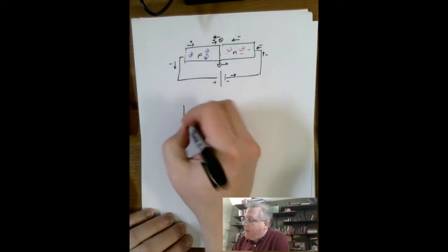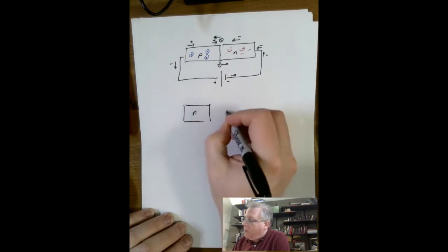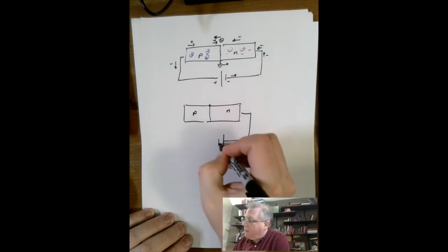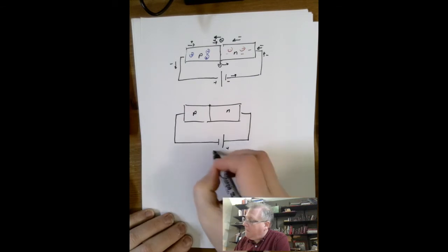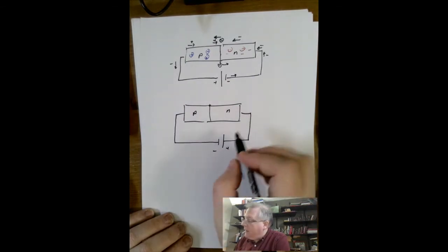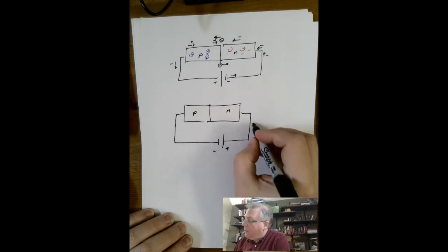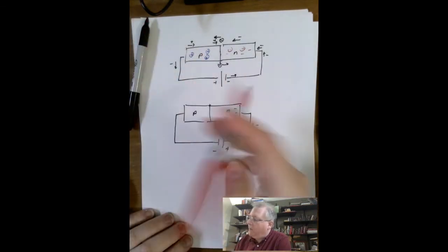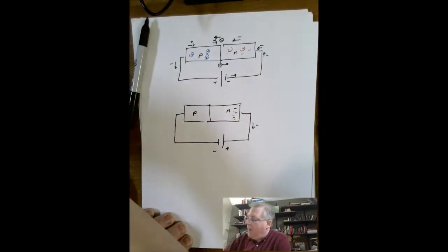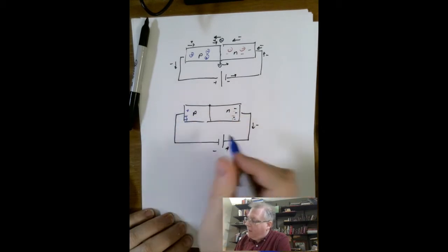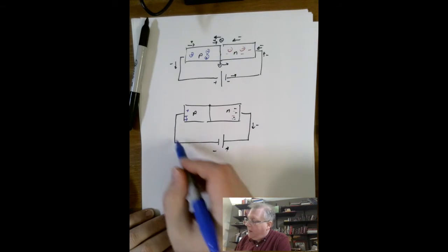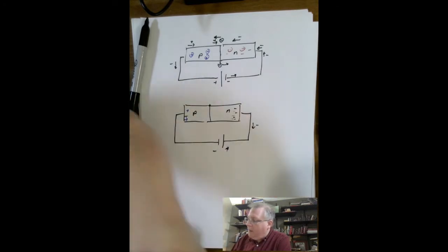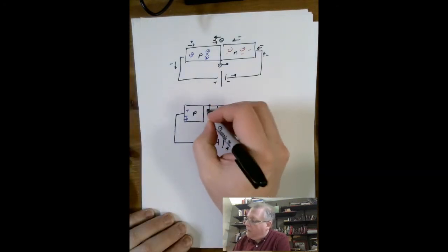Now, if we have the same situation and we put it under a reverse bias, that's the positive over here and the negative over here. Right, remember how the battery goes. So this thing now is attempting to pull electrons this way, and so electrons will get pulled over to the right-hand side of the N-type. Oh, let's use colors. Colors are fun. So N-type over here, and this thing is attempting to push electrons in this way. So holes are getting pulled to the left. So in the middle of this, you have what we call the depletion zone.